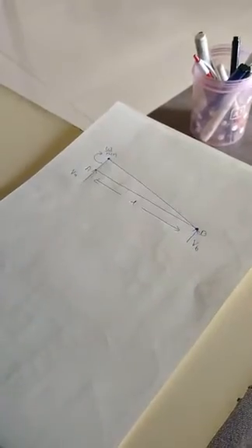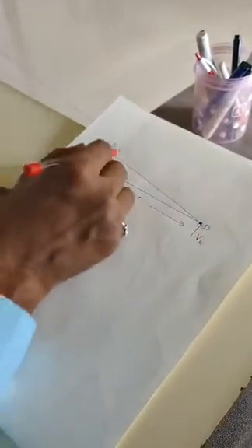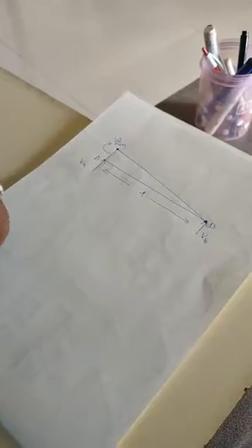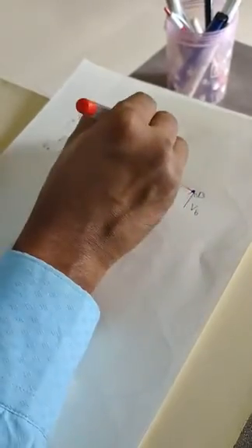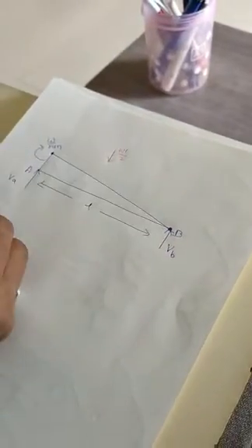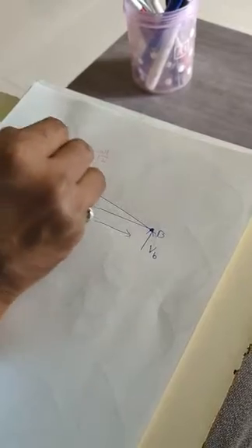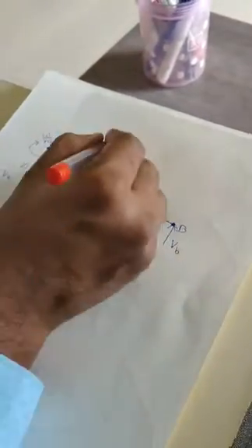So we know the total load due to the right angle triangle is nothing but the area of the triangle. That will be W into L by 2, base into height by 2. So this is the total load I am showing here: WL by 2 will be the total load. And where does it act? It is always at the centroid of the triangle, that is at L by 3 from end A. This load I have shown to calculate the reaction values.